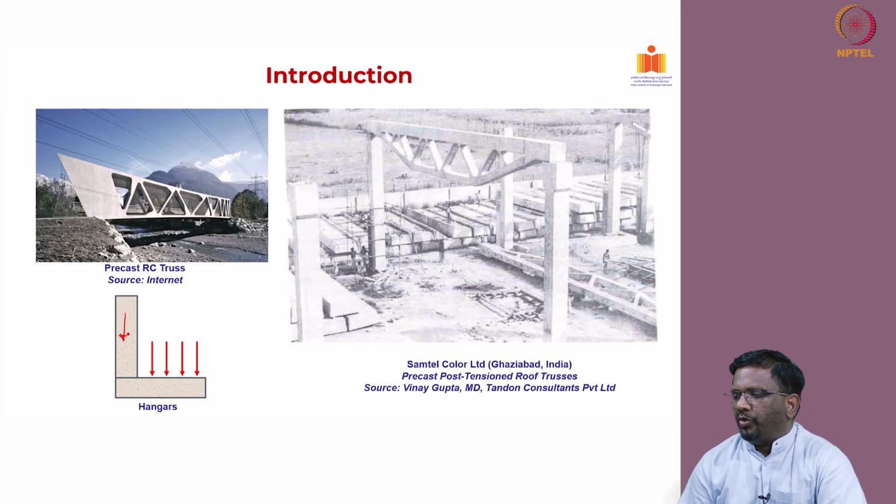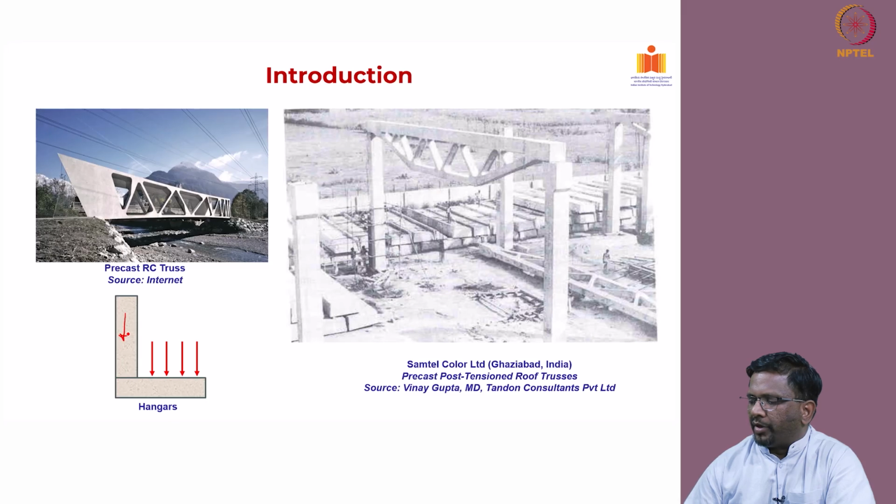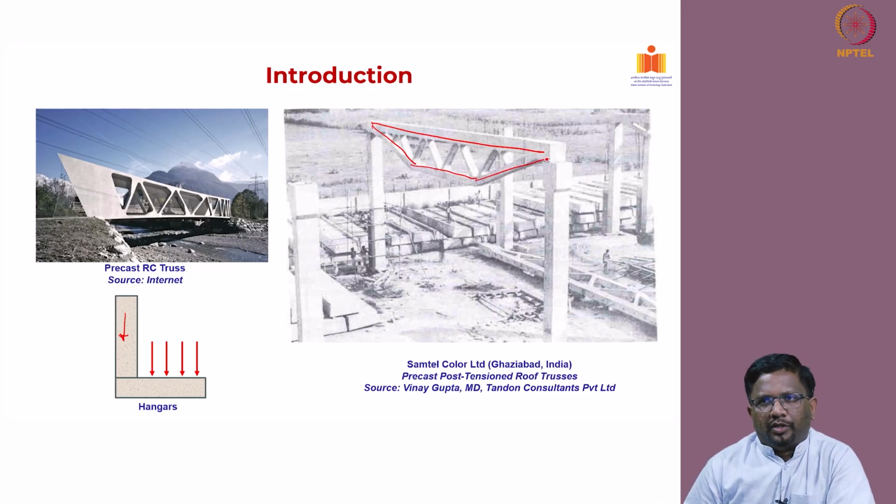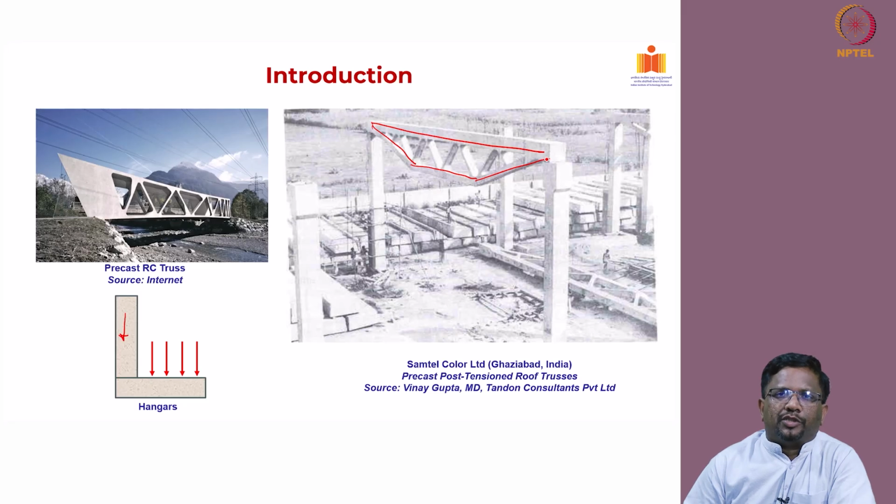Now, this is one more very interesting case of Samtel Color Limited. You can see a nice roof truss element which is made of reinforced concrete, actually post-tensioned with prestressing steel. You can see that the tie elements are usually tensioned, so that they are always going to be in compression under service loads.